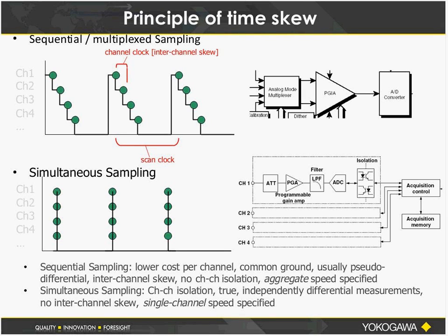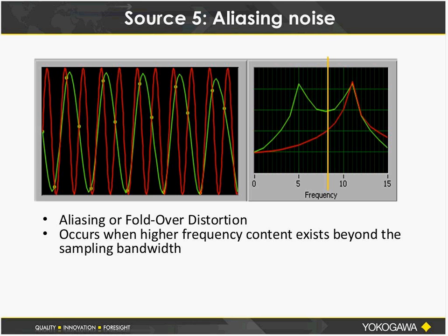So again, keep that in mind, and if you have a device that is pseudo-differential, which will be explained in the manual, then be aware that there will be time skew between the plus and minus terminal of the same channel even.